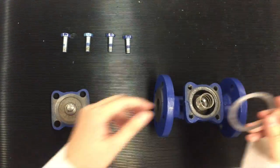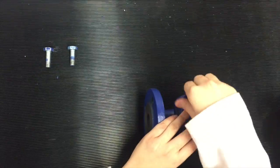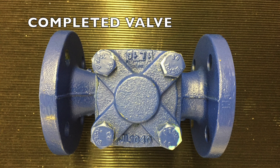After putting the seal onto the housing, secure the cover onto the housing using 4 hexagon screws. Loosely screw all 4 hexagon screws to secure the position before tightening them. A completed non-return valve looks like this.